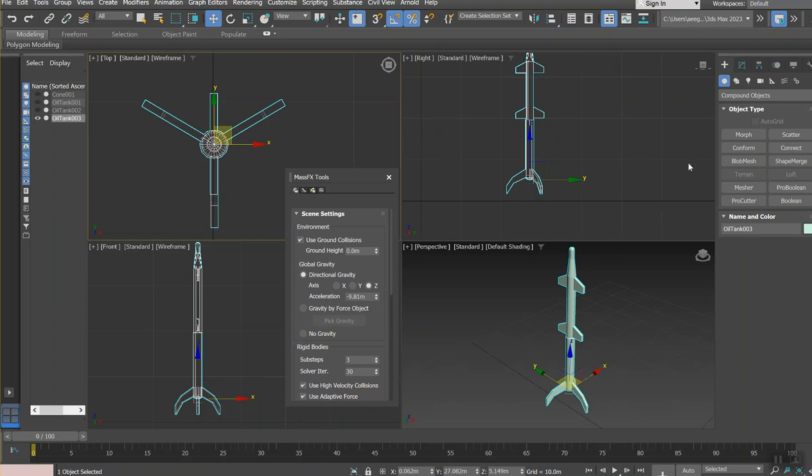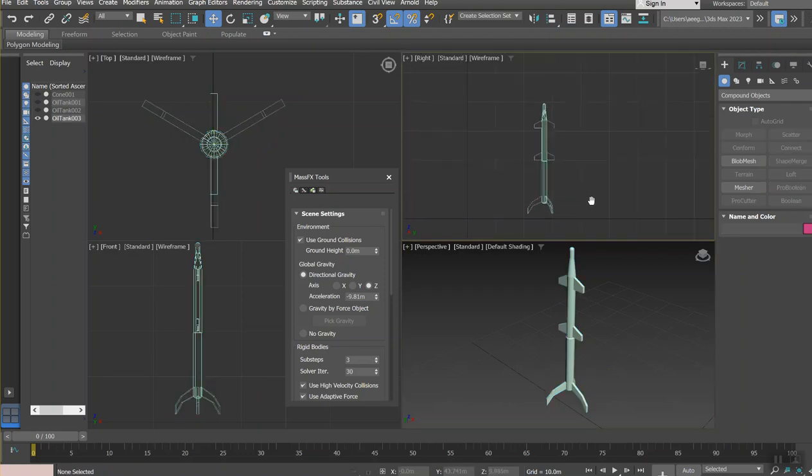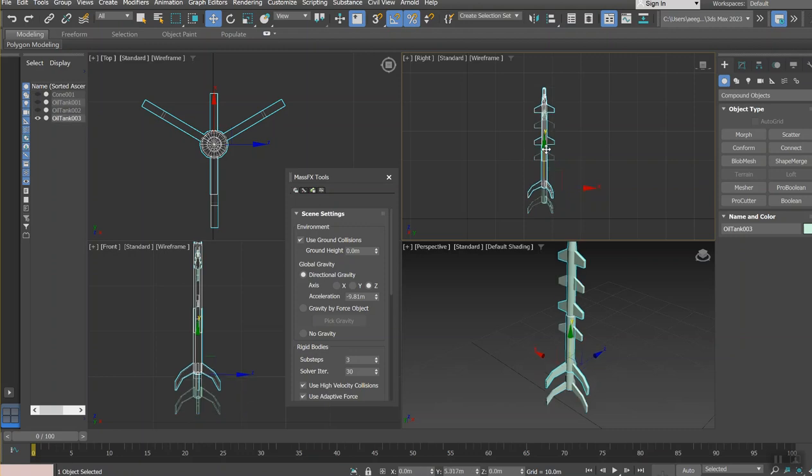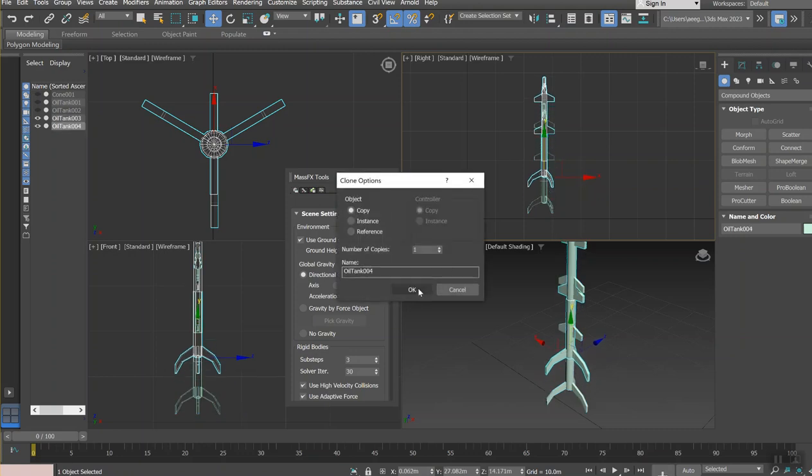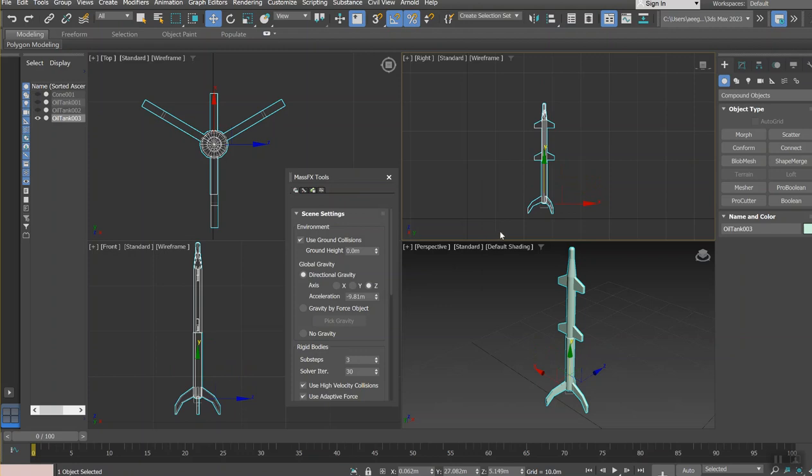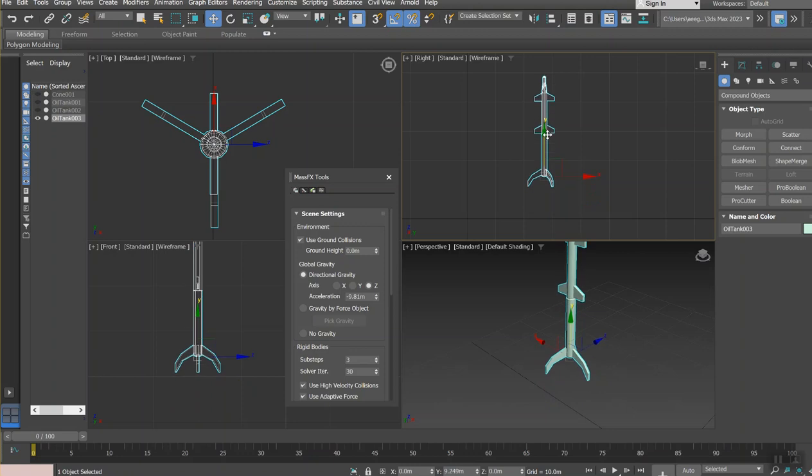First of all, we're adding mass to this entity, and the entity itself is supposed to gain a particular weight, and then we're expecting this entity to fall on the floor, on the ground. So for that to happen, perhaps we need to move it up a little bit higher. And when I'm doing this, I'm going to press the shift button to send it up in the air a little bit. I'm sorry, do not press the shift button. Just simply drag it a little bit higher.